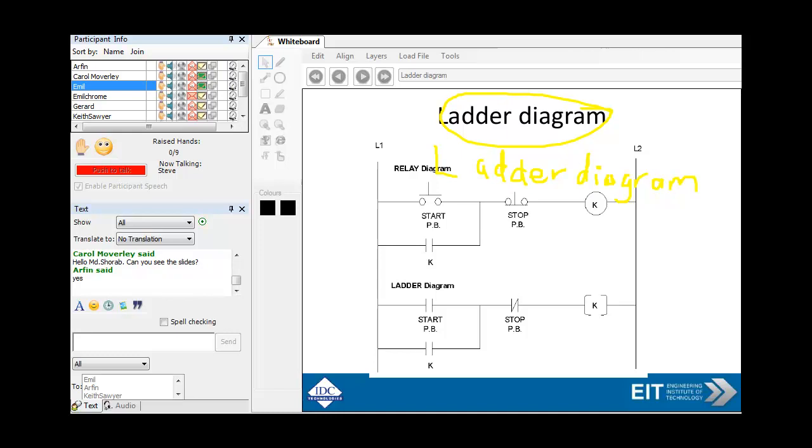Brilliant. Okay. Excellent. Thanks. So what we want to show you there is that when you've got an emergency push button, you obviously want to make sure if the cable's cut or broken, the PLC would immediately trip out the contact. So what we're showing you here is that power flows from left to right. You push the start button. The stop push button is healthy. In other words, it's energized. You're happy. No one has pushed the emergency stop, and then you energize, and then you have a process called sealing the contact, which means that once the contact's in, it will be locked in until you push the stop push button. Very important. So that's an important part of the diagram.